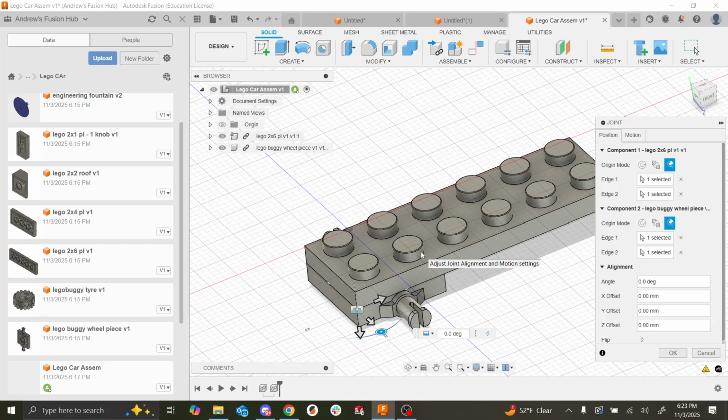And then what I normally do is near the end of the design, I'll start making the part look pretty, and I start adding chamfers and fillets on a lot of edges. And if you do that, it'll break the joint tool in Fusion because you're essentially deleting the edges that it is referencing, right? That's what I don't like about this tool.